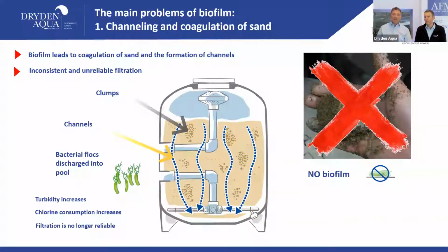I can tell you this, in aquariums or in aquaculture, very often we use fluidized sand beds to grow bacteria, where you get the water from below to up. You always fluidize the sand bed to grow heterotroph bacteria on it, because they're eating organics.